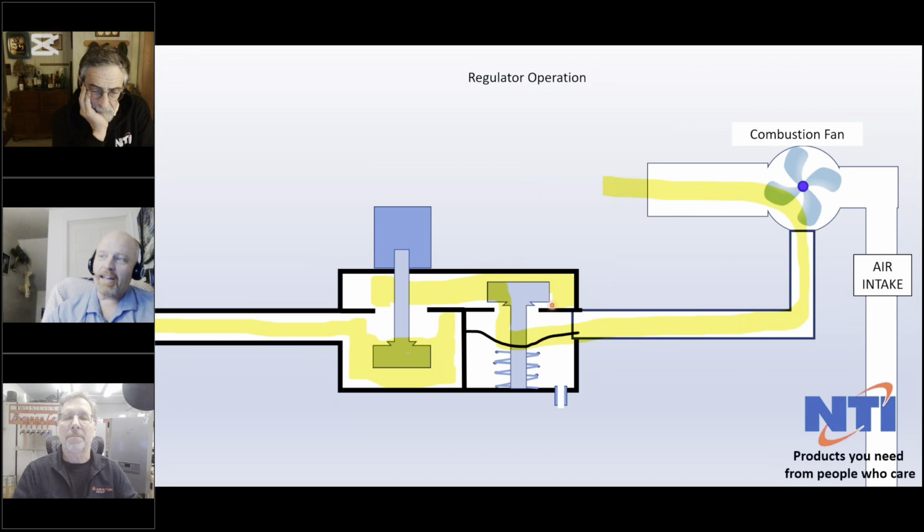Cool. Question, Dave. That air vent, which previously was connected to the intake air because it was basically sealed combustion, is now just open to the cabinet, correct? It's open to the cabinet, but because the cabinet now represents the air intake, the net result is the exact same. So if you can imagine, if I was to extend this air intake to cover the entire valve, then this tube, even if it wasn't connected to anything, would still be referencing the air intake pressure.